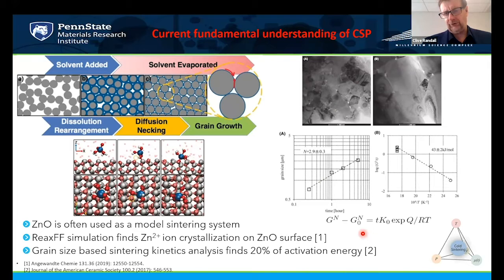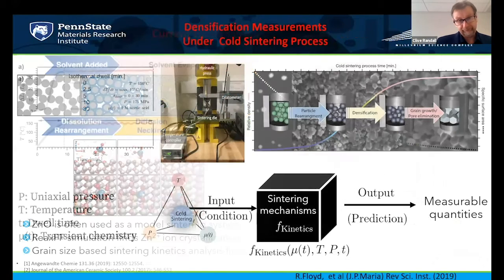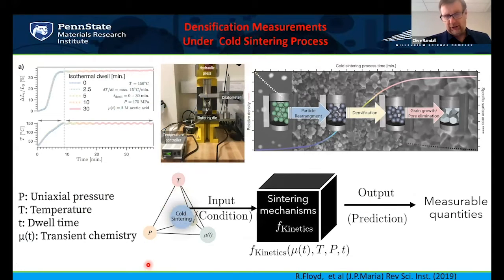But on a macroscopic level, you can see the sintering process scales with the traditional scaling laws of sintering coarsening, and the activation energies, though, are orders of magnitude lower than what you would expect, right? So the activation energies are severely reduced. So the parameters are the application of pressure, the time, the temperature, no surprises there in terms of sintering. The real difference is really the chemical activity of that sintering aid that then interacts in a non-equilibrium manner to then drive the densification process.